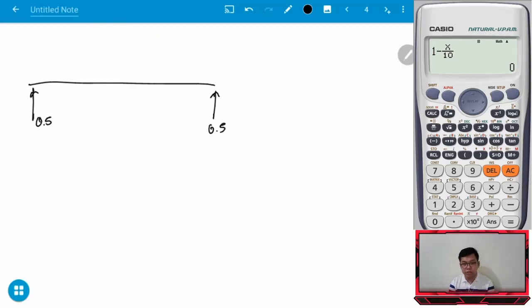In the method of sections, simply cut the beam, like you learned in the method of sections for trusses. Actually, you can use this here too. So cut the beam, and when you cut the beam, the internal shear and moment will appear. If I solve for the shear at C in our problem, I will cut the beam here at C. When I cut the beam at C, this is what happens.